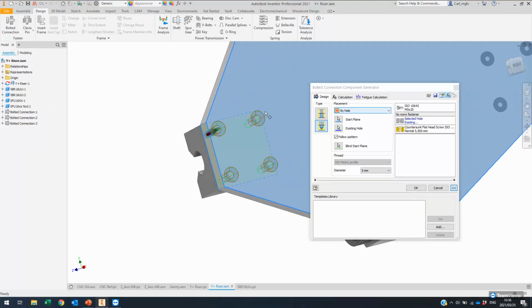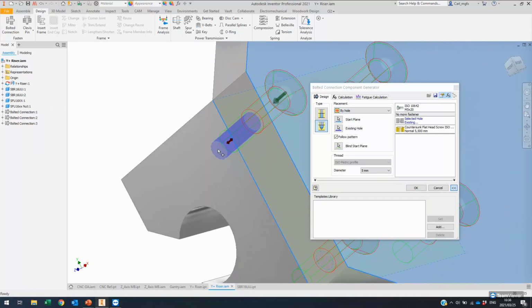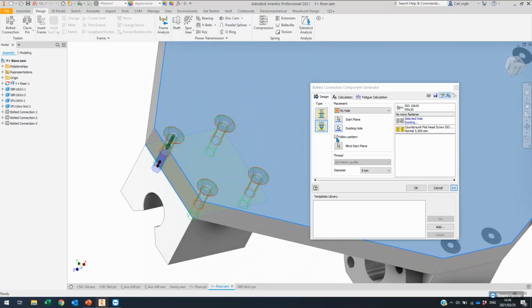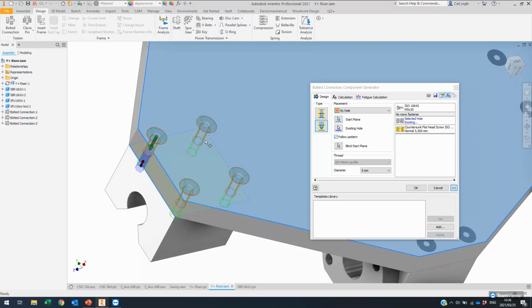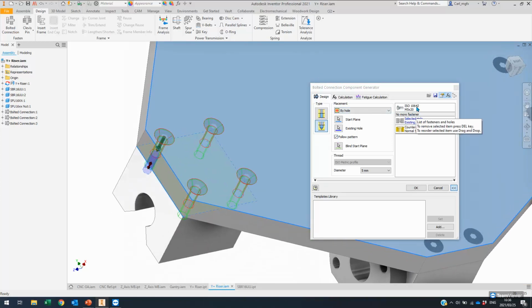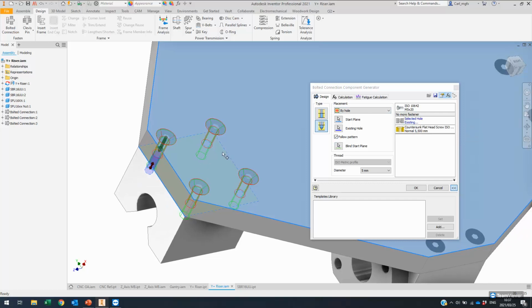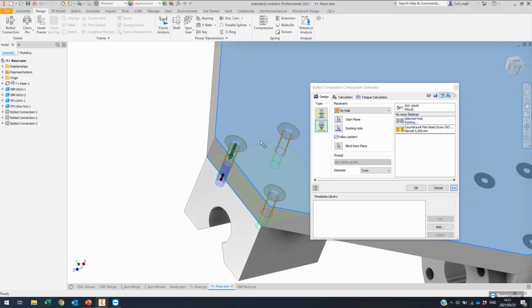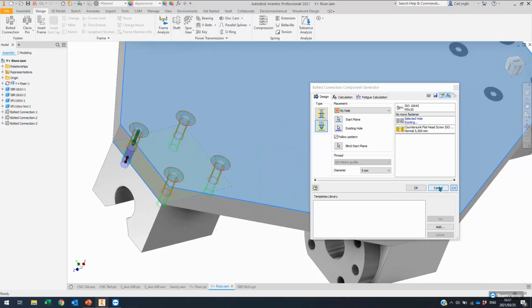This bolted connection is placed in our hole. So it's placed using that hole on the downloaded library component, and we're following the pattern there, so it places down all 4 of them. And the bolted connection, once choosing the actual bolt itself and setting it up, will drill any holes that you need. So we can actually see here, it's going to drill the countersink flathead screw hole through there for me.